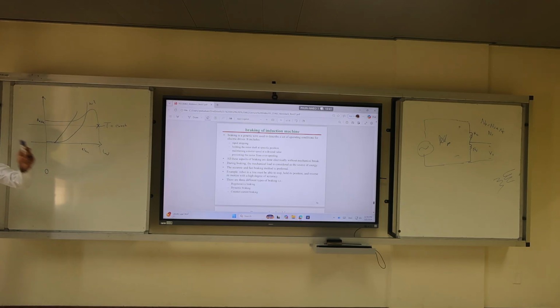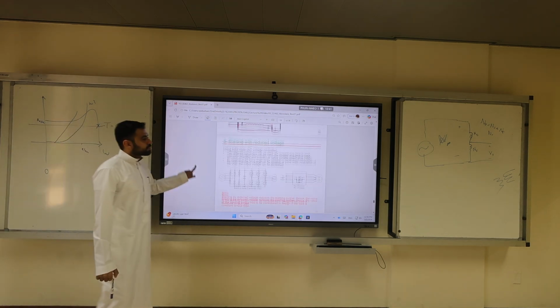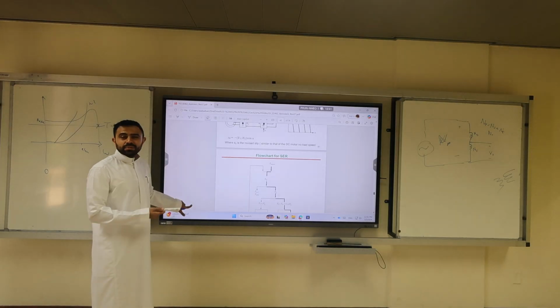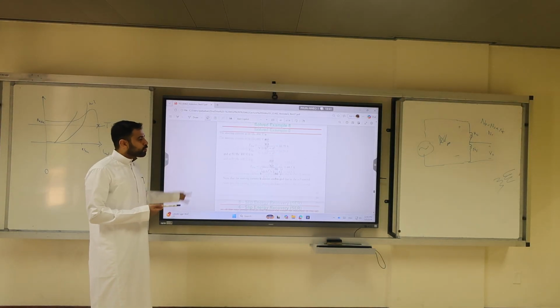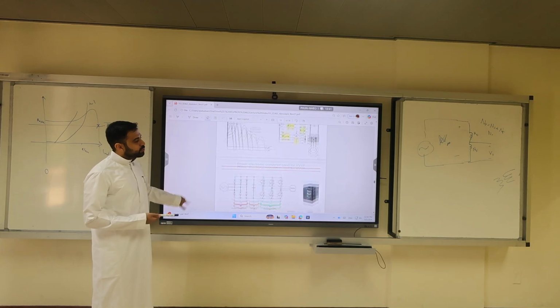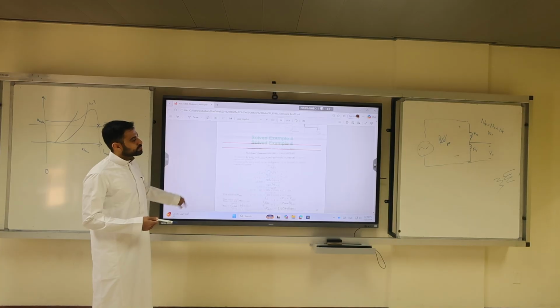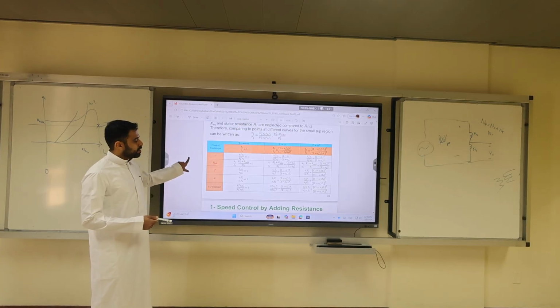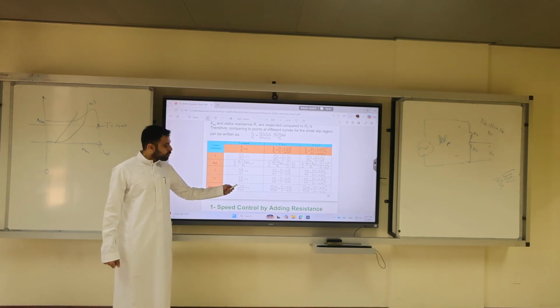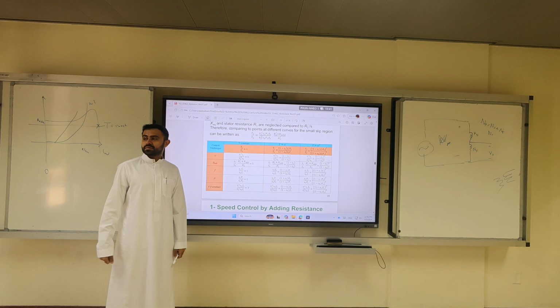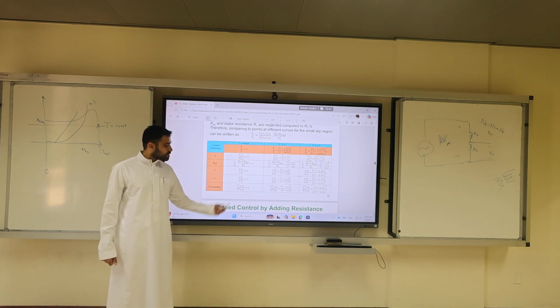And how to do it? You go to the table. So for example, if I ask you in the quiz, all the examples we did were linear, right? So focus on the linear. If I ask you in the quiz, no, not the linear, constant. If I ask you in the quiz, you're operating at 440 volts, 60 hertz, at slip 0.02. How much slip is needed to operate at 450 hertz? Clear? Yes. You just calculate S2.